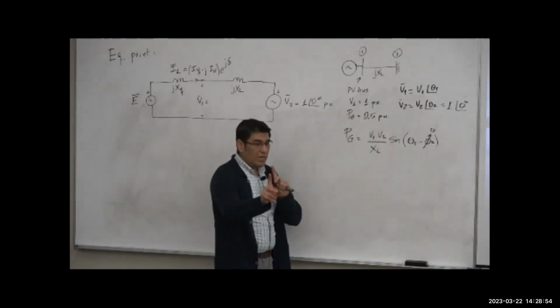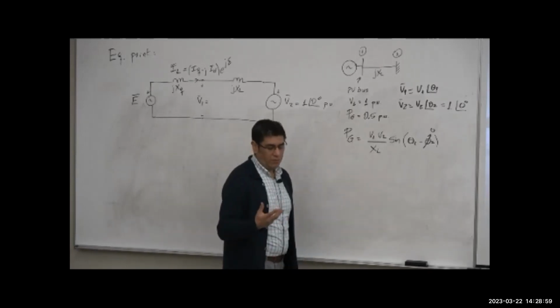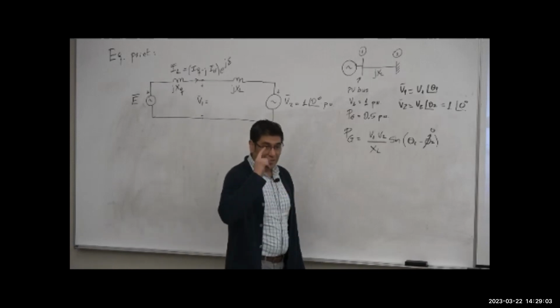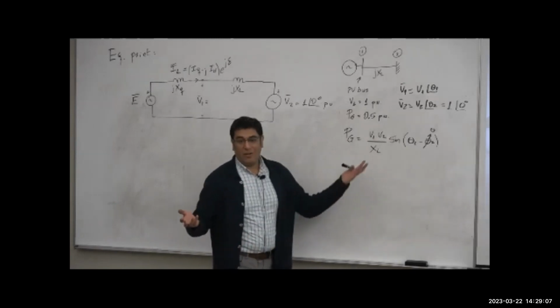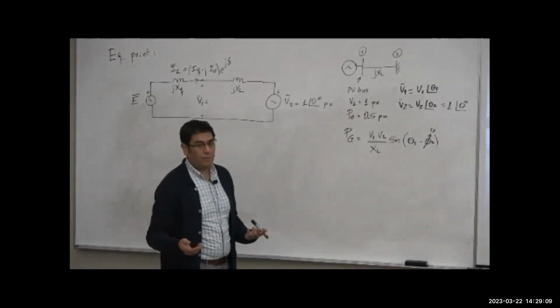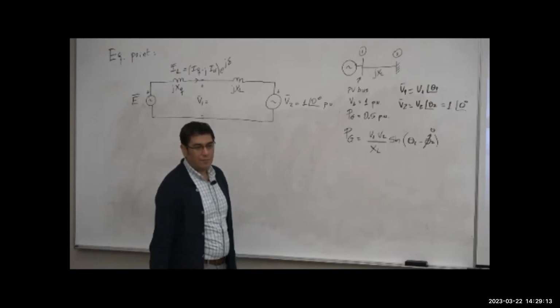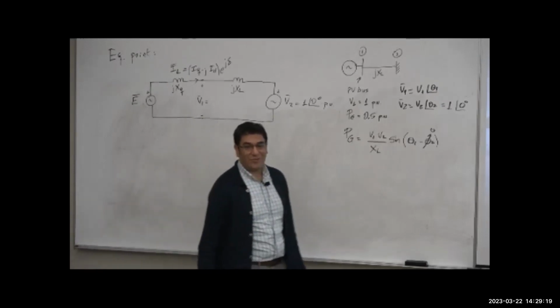What we need to be careful with in the implementation is that this is a PV bus. Therefore, there is just one unknown. You need to get a complex equation for Gauss, for example, but you just care about the angle, not the magnitude. What about the Newton-Raphson? How many equations do you have? Just one unknown. Very strange Newton-Raphson.